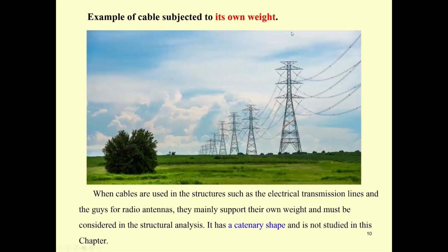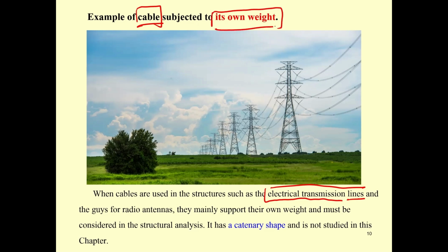And then there is another thing for the engineer who builds electrical transmission lines and power lines. This kind of cable is not subjected to concentrated load or uniform load; it is subjected to its own weight, and the shape of this cable is in the form of a catenary, different from the parabolic shape.